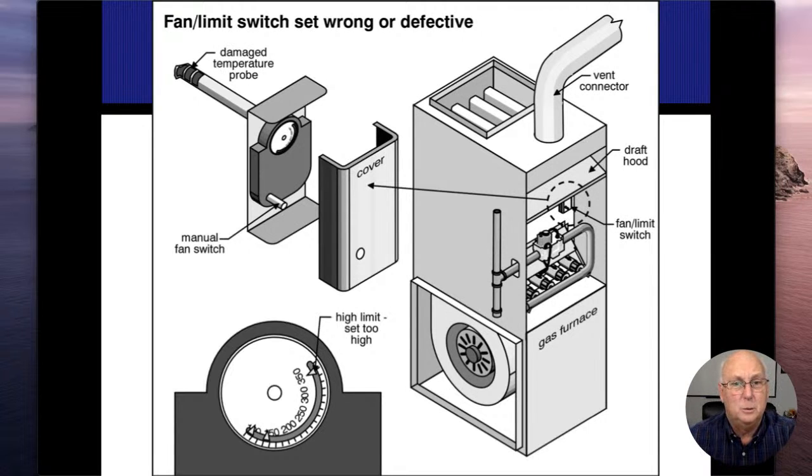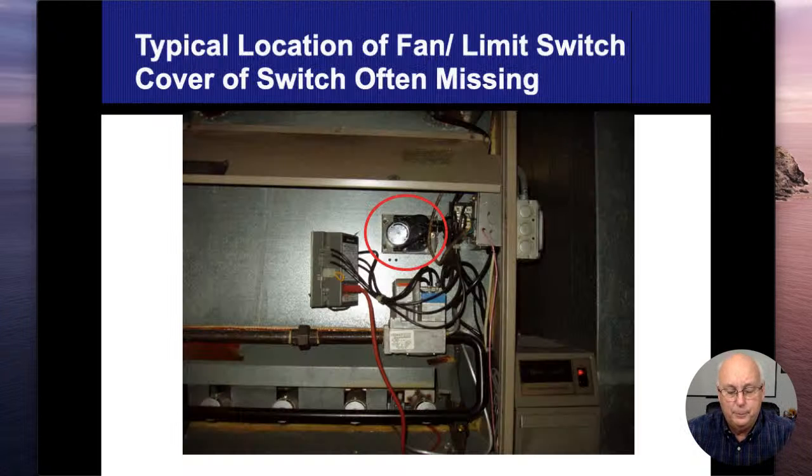I've never run into this where this thing was set off that much. I do pull that cover off and check those numbers if I see an old furnace like this, just to make sure it's not there. If somebody has this set up to 350 degrees just to keep that thing going, that's not a good thing. They're really turning it into a gravity furnace, but the amount of heat that's there is not going to be a positive thing.